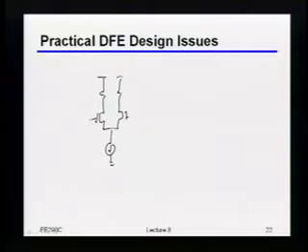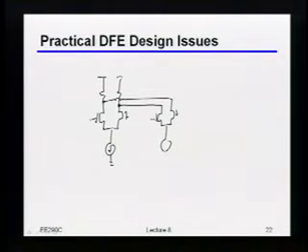All right, so if I look at my DFE summer, and let's just do it with one tap, although in reality you should keep in mind I may have many more taps than that, my DFE summer looks something like this. So those are my output nodes, and of course my inputs. Now remember, you don't necessarily know ahead of time which channel you're going to be operating on, at least not if you want to build a link that would work in many different possible usages. Well, that means that this thing down here is going to have to be programmable.